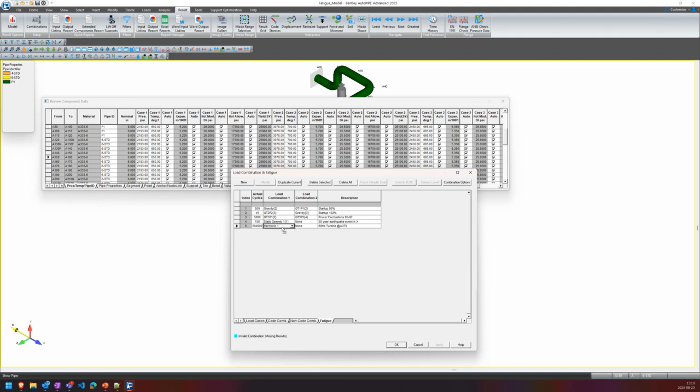I want to specify also that if you're using one of our fatigue curves like ASME Section 8 or ASME B31.3, one of the equation curves that does not have a FAT file attached to it, those typically will use hot material properties in the equations themselves. So if you're using a reversing dynamic load, like say, for example, this harmonic case, and the same with static seismic, AutoPIPE is going to assume that this is running at ambient temperature. So you'll effectively be using cold modulus and cold yield to determine the number of cycles that are allowed for that load set. So what I want to do is include temperature.